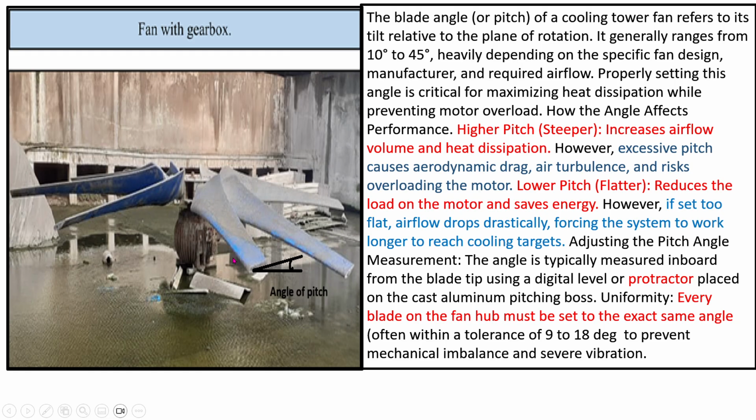Earlier it was solid type blades. Due to heavy weight, power consumption was more. Now the blades have become hollow, the weight has become less, and performance is more or less the same. That's why the vibration as well as the motor consumption will come down.